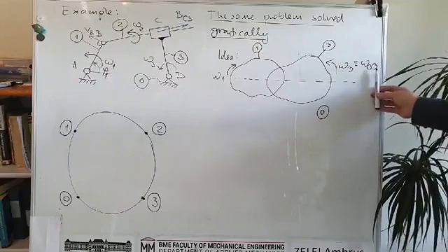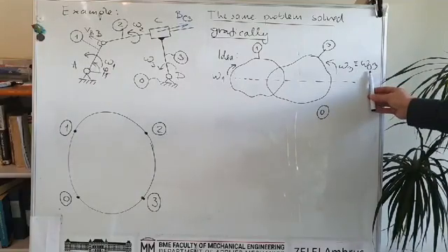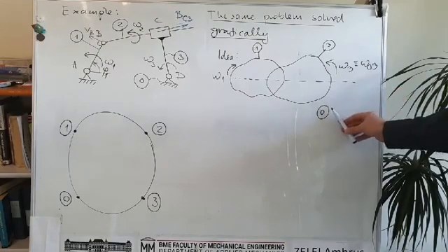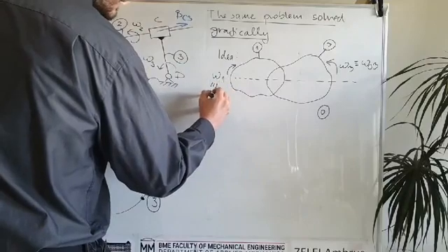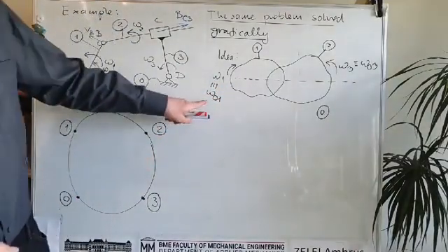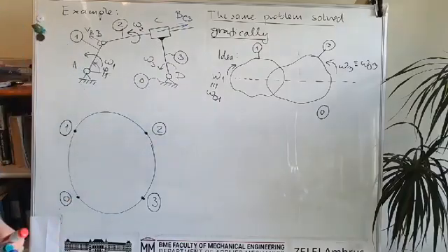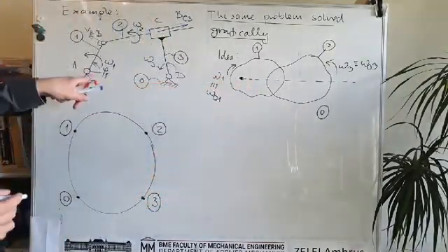So this means that this is an angular velocity of rigid body number 3 relative to the ground, of which the index is 0. And this is the same here, so we can say that this is a relative velocity relative to the ground. And then we will know that there is some point where it is fixed to the ground, like here.